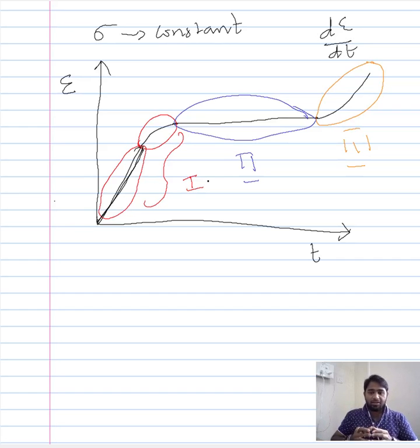Now, the time taken for this instantaneous creep, or this sudden strain exhibited by the material in response to the sudden imposition of the load, let us assume that to be Tin. Now, there is an overall period of time during which the material behaves and evolves and ultimately fails. So, for a given loading condition, over a period of time, the material evolves and ultimately fails at a particular temperature, and this overall time taken, let us refer to that as Tc.